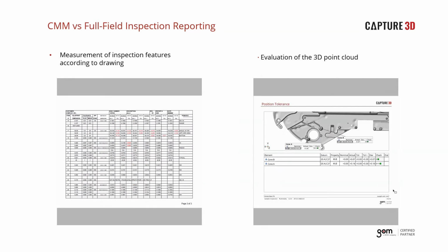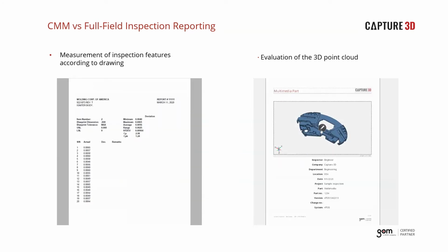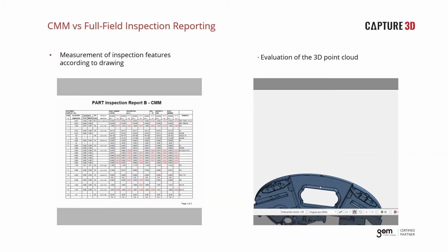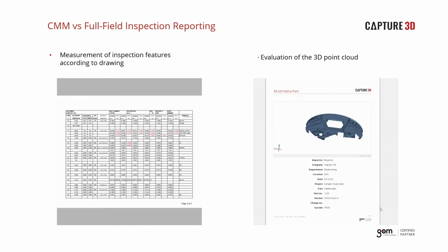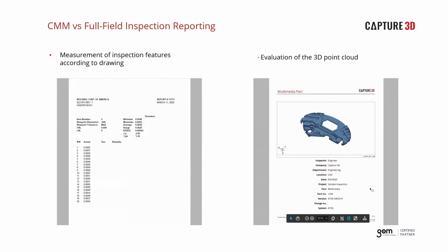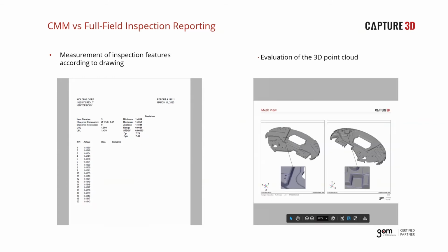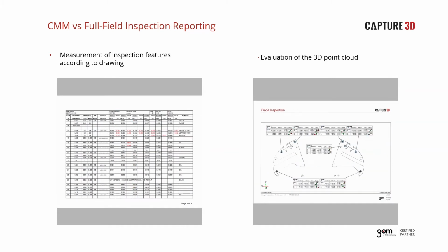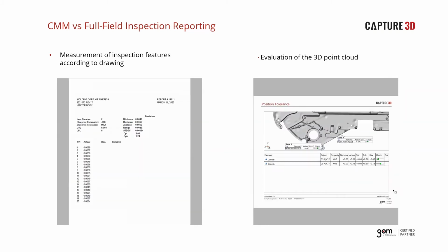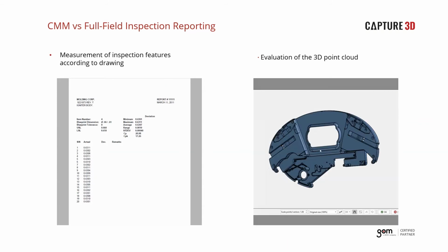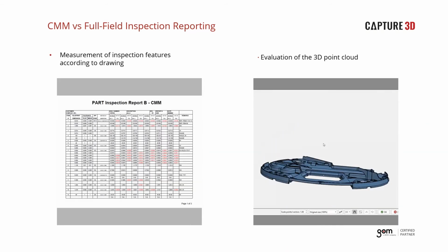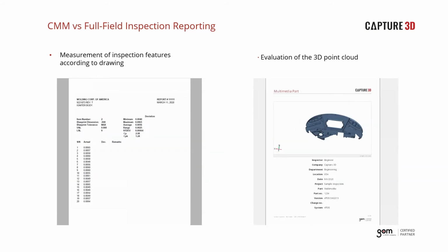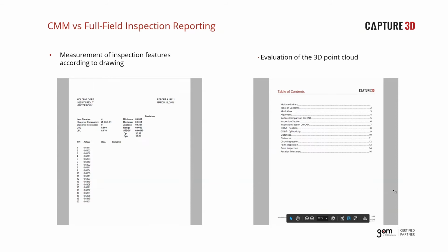This is greatly beneficial for the end user because you can go back to the data set without rechecking the part and do a remeasurement of that part. With that, you can also add to the existing or create a new measurement report, which then includes the original areas of interest along with the new ones that were added to the visual report. A little hidden gem inside ATOS is the ability to create 3D PDF reports within the software for a nice, innovative way to present our data set.